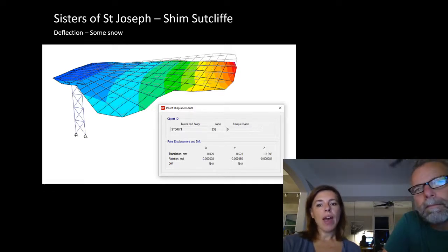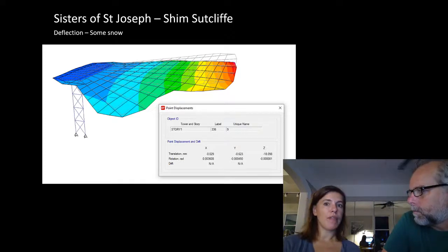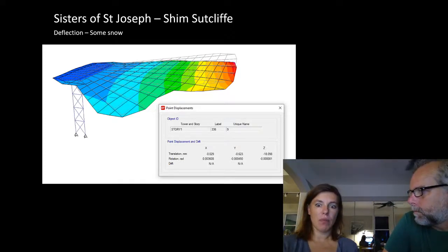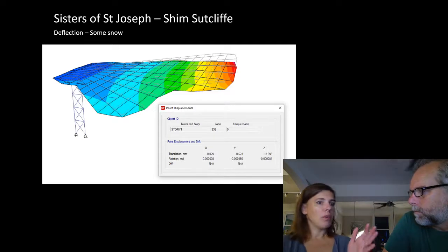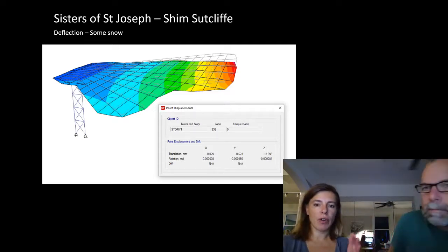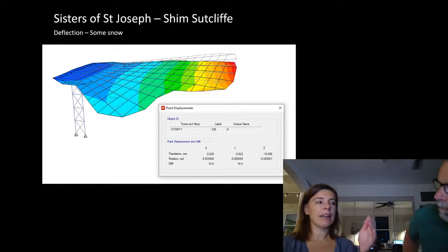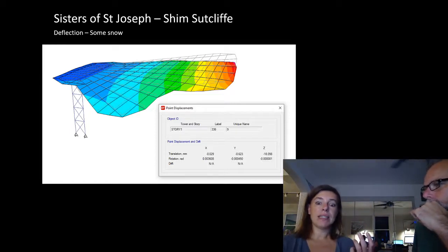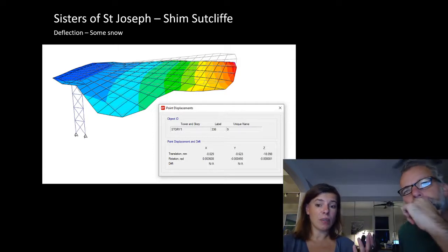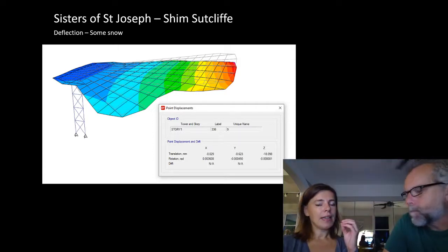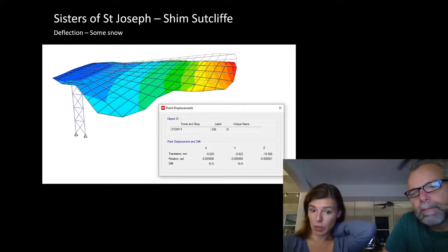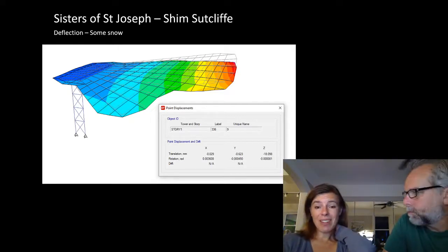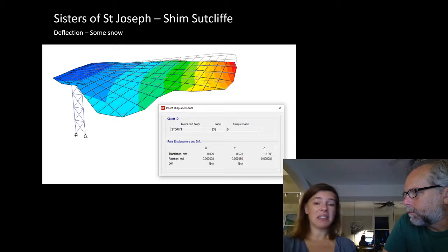I was with Howard Sutcliffe when I took that photo, and I was like, oh, I'm really sorry. We should have written some criteria for heat progression and how to limit the possibility of oil canning due to welding. I didn't even think to add that into this, which you can do. It doesn't eliminate it, but it can give them some controls on it. Howard was like, you know what? It's a real thing. It rusts. You can see some water, it dries up pretty quick. He's like, I'm okay with it.